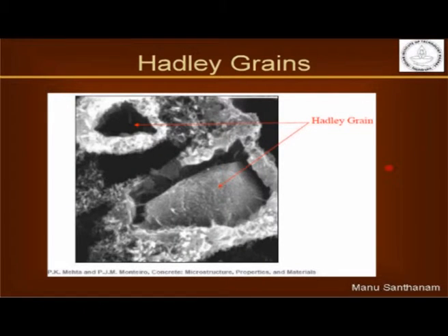Now these are some pictures taken by microscopy of how the cement is hydrating. I told you earlier that the particles of the cement, that is C3S and C2S, dissolve outwards. Okay, this is showing you one such particle which is dissolving outwards and forming these hydrates on the outside. These are the hydrated particles that are forming outside.